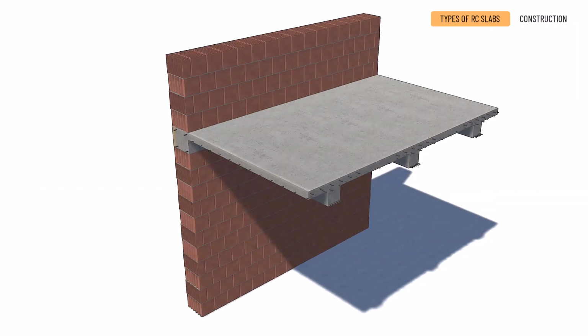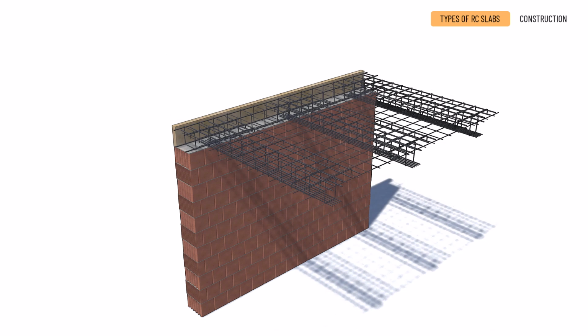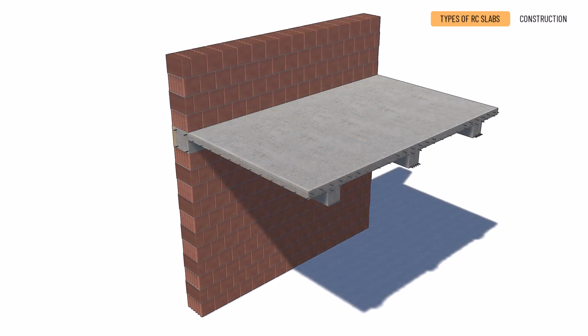Downstand reinforced concrete slabs. Here, the ribs are located at the bottom of the slab. Together with the ring beam, they require a complex geometrical formwork, allowing to make the reinforcement and carry out the concreting in one step. The density of ribs may vary. Often, stronger beams, 15 to 40 centimeters high, 15 to 20 centimeters wide, are placed at an axis spacing of between 1.5 to 2.5 meters.